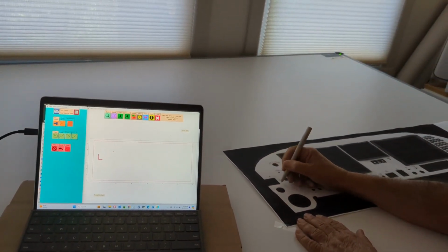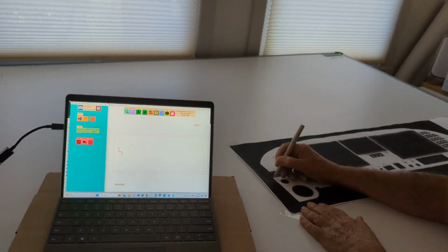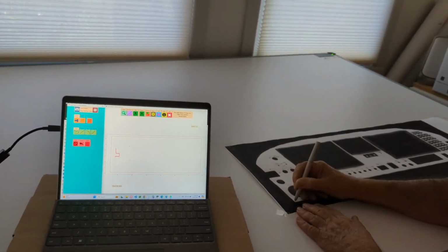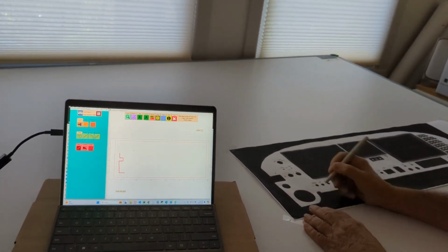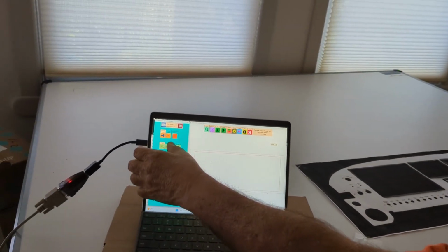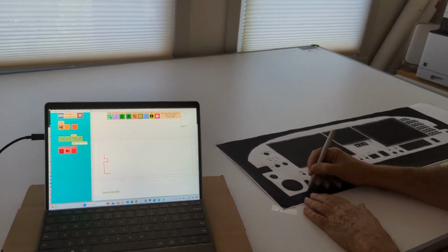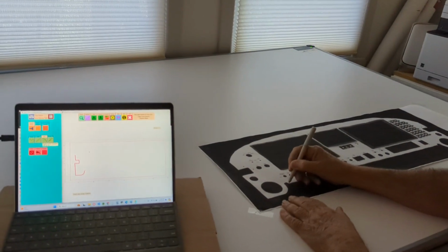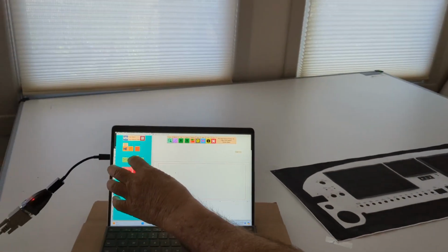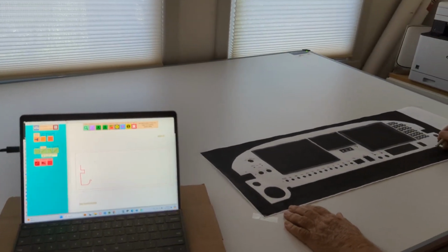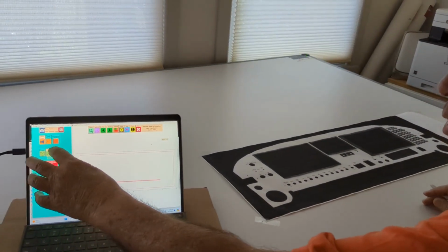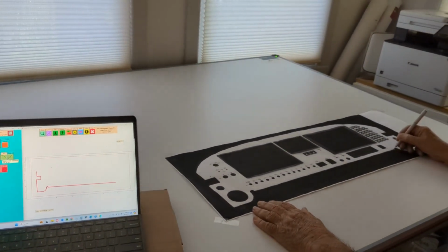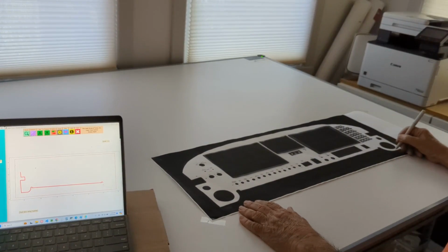I'm just going to digitize those corners using the tracing method, and it will automatically connect those with straight lines. Now down here I have a couple arcs, so I switch to arcs. Do the midpoint of the arc, endpoint, midpoint, endpoint. I now switch to a line, go all the way across the bottom of that panel. And then I have a couple more arcs on this side. So that point, that point, that point, that point.